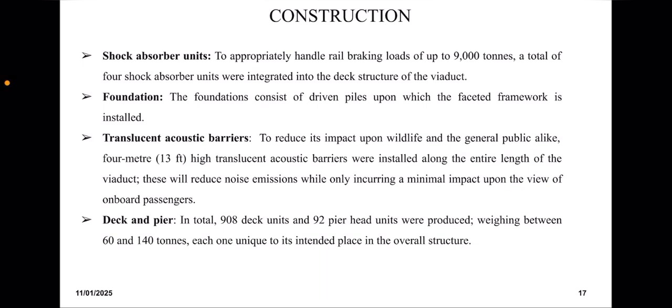The foundations consist of driven piles upon which the faceted framework is installed. To reduce its impact upon wildlife and the general public alike, 4-meter high translucent acoustic barriers were installed along the entire length of the viaduct. These will reduce noise emissions while only incurring a minimal impact upon the view of onboard passengers.